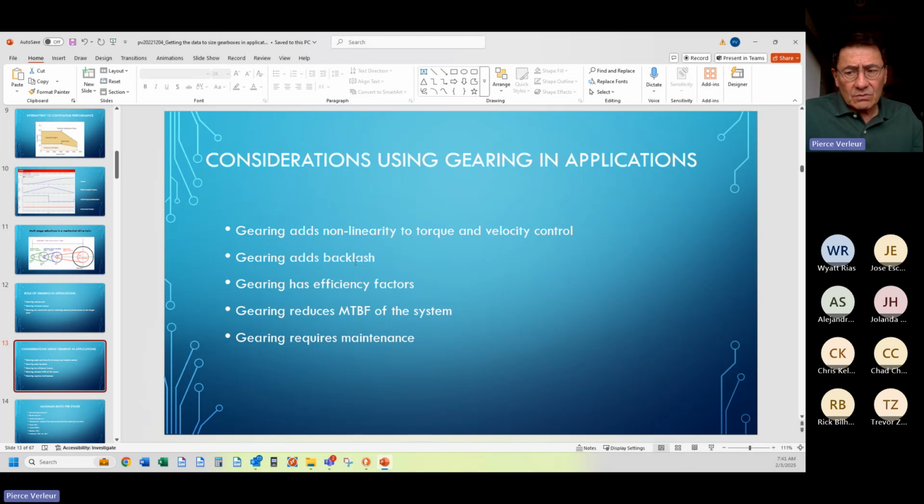There's another case where backlash can be quite deleterious, and that is when you're doing high cycling applications, because you're driving in one direction and then you're slamming it into the other side of the gearbox gap, and you accelerate across that gap and hit the other interface with quite a degree of peak force. And you keep banging those gears back and forth on each other, and eventually you're going to wear them out and break stuff.